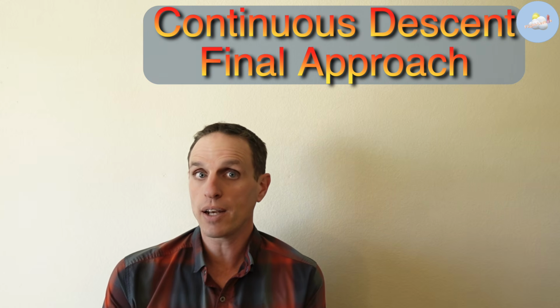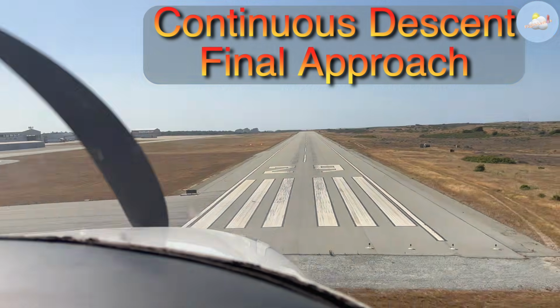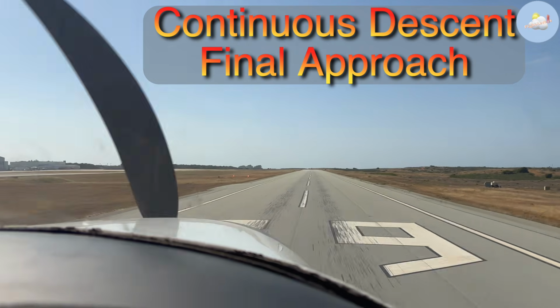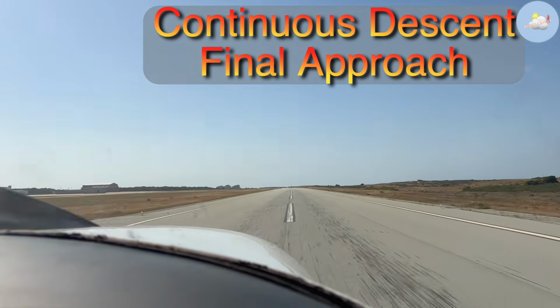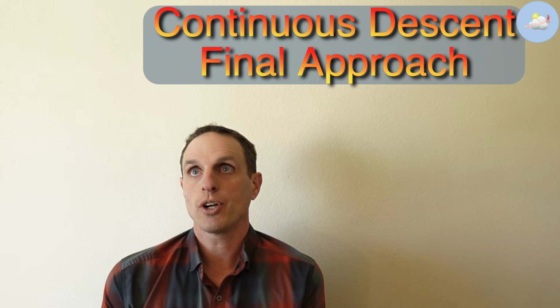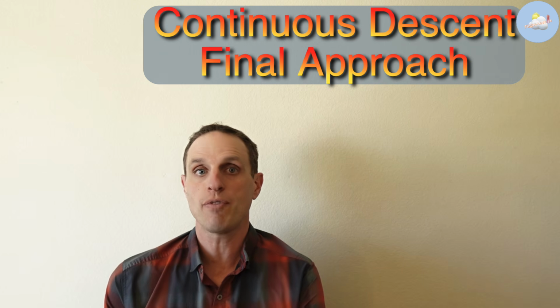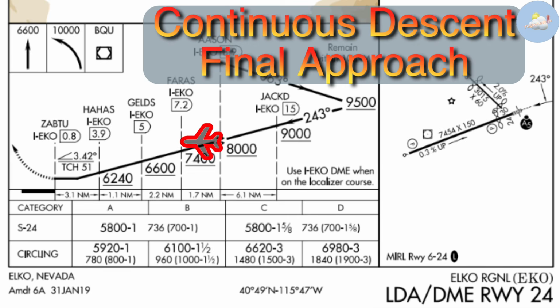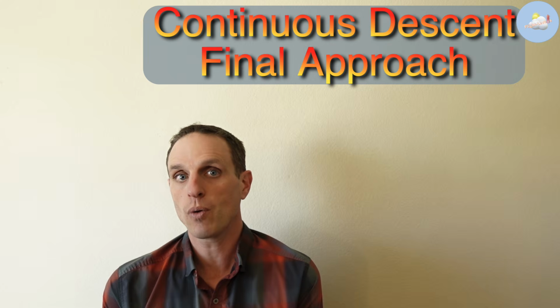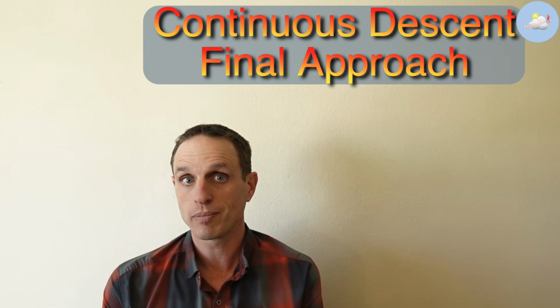Now, the downside of continuous descent final approach is that with that goal of seeing the runway environment and ultimately landing, you end up at your minimum descent altitude for a very small amount of time. So your chances of seeing the runway environment may be reduced if that moment that you get down to the minimum descent altitude is also the moment you have to execute your missed approach. So there are pros and cons to both dive and drive and continuous descent final approach.